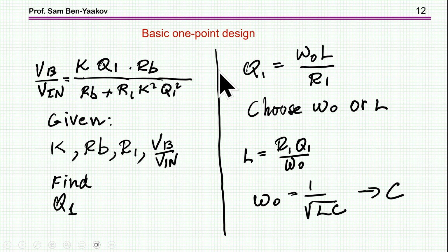So we are talking about working at resonance for given requirements like battery voltage, input voltage, etc., and charging power. And from this expression, we can find what the inductance and the capacitance of the antenna should be to get the optimum operation. And by optimum operation, I mean having the lowest losses. I'll talk about it a little bit later on.